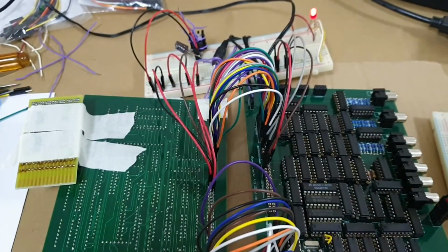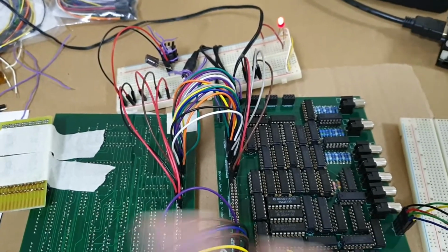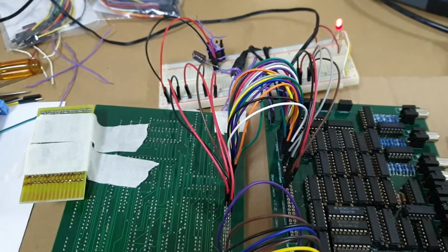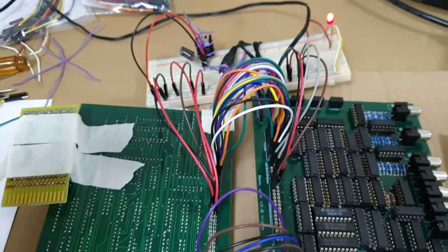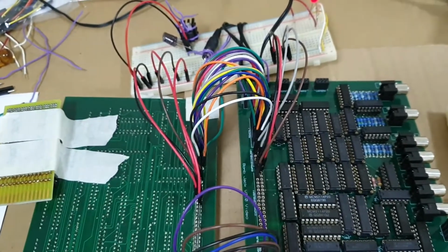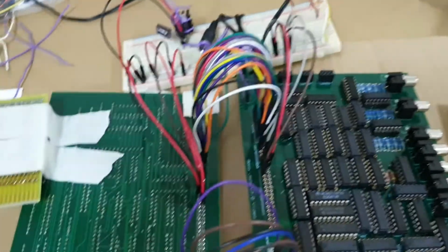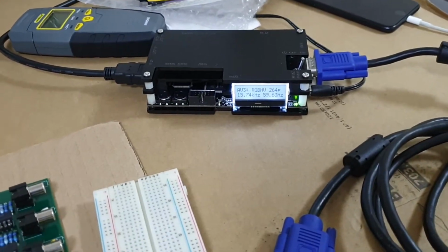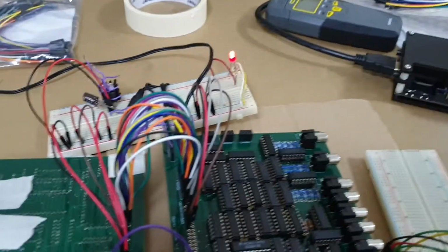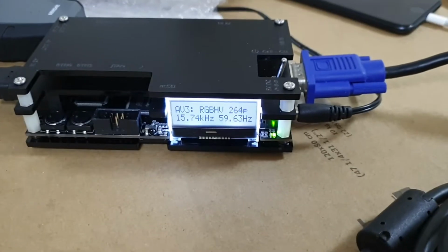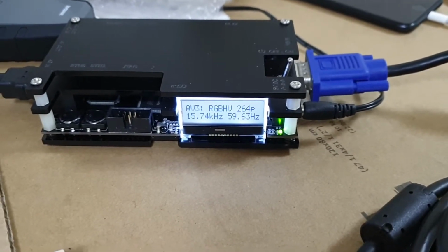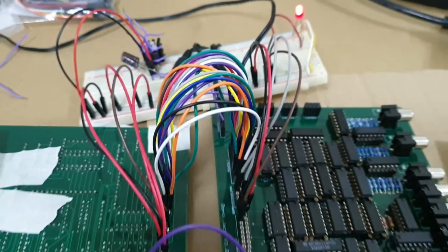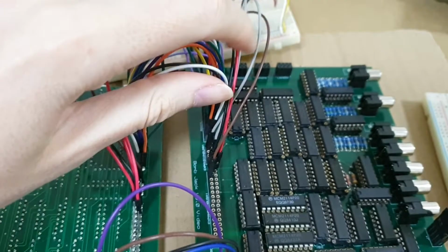So when I was experimenting with this open, reverse, upside-down board arrangement last night and early this morning, I found that the design, with quite long wires bridging the gap here, was quite unstable. The video conversion box was showing that the video signal was oscillating quite a bit. Sometimes the timing would go down to 57 or something like that hertz, and sometimes it would pop up to about 73.